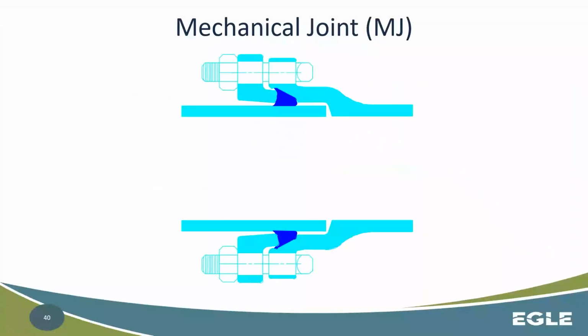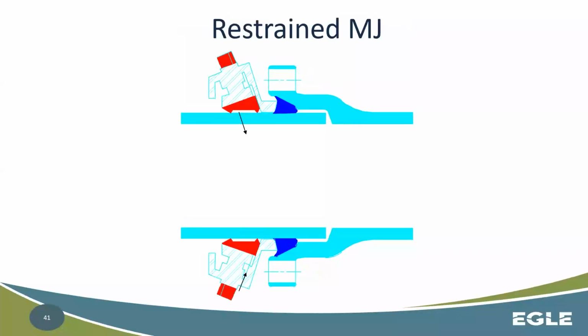Okay. So again, mechanical joints. This is a good overview of it. This bolt and nut situation here with the bell and spigot end is not really touching this water main portion here, but rather is pushing down directly on this gasket. Okay. So it does not restrain thrust. It merely just holds that gasket in place, basically just to make sure that there's a good, adequate seal going on.